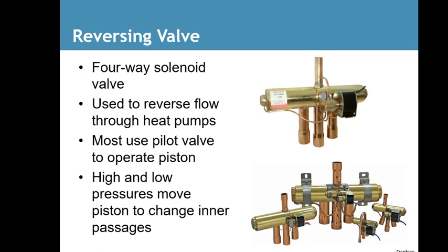Reversing valves. Four-way solenoid valves used to reverse flow through heat pumps. Most use a pilot valve to operate a piston. High and low pressure move pistons to change the inner passageway. We talked a little bit about this in the labs for this module, and you'll start seeing these more and more. Florida doesn't have a lot of heat pumps, but they do exist.